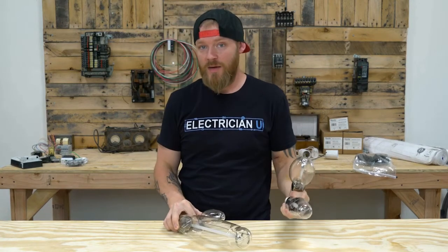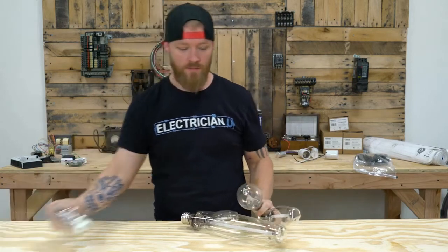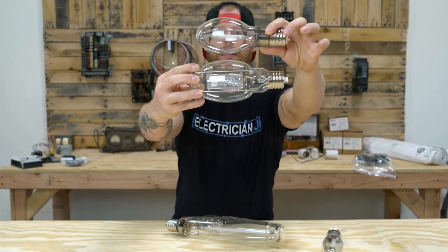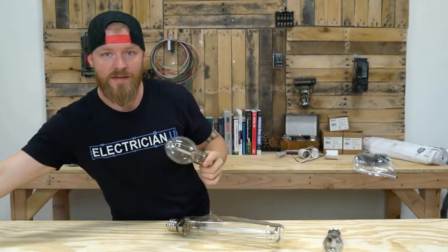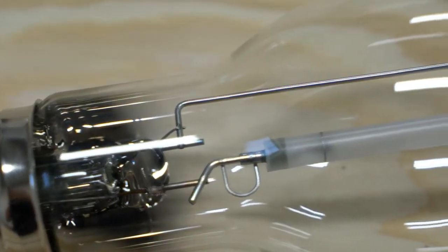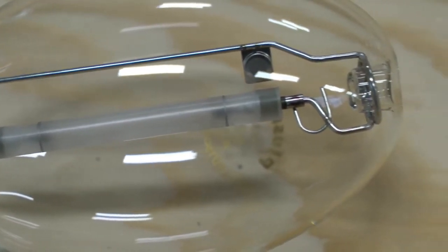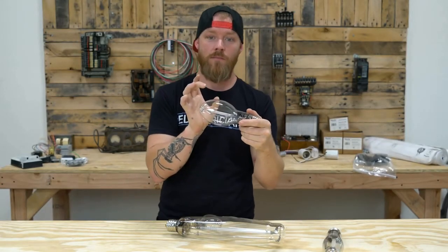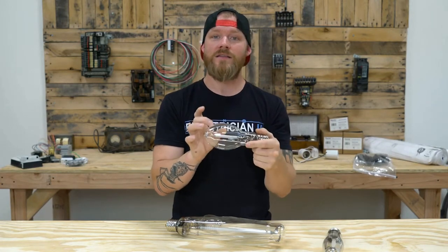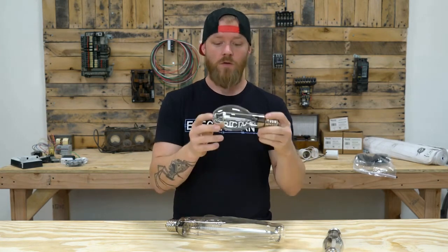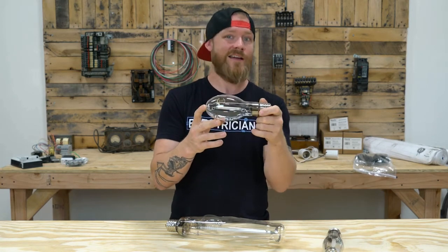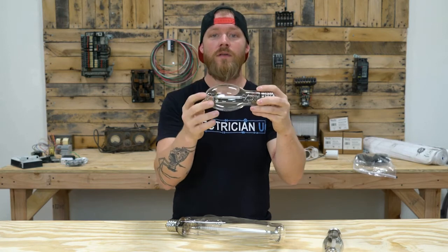High pressure sodium is another type of high intensity discharge lamp, much like the metal halide, but you can tell that the arc tubes are completely different. A high pressure sodium has a much skinnier tube, and you can tell that tube is not clear. It's not made out of glass or quartz. The reason is that with sodium and mercury on the inside of this thing, you need such a high amount of heat that glass or quartz would just break. So they came up with a specific type of ceramic, like alumina oxide ceramic, and that is what that whole tube is made out of.